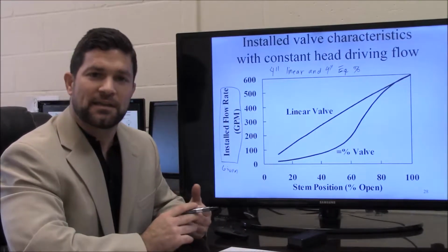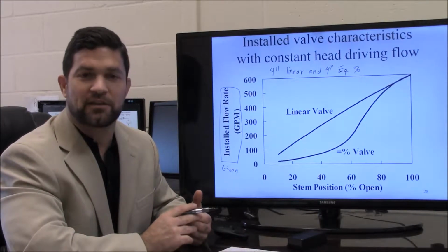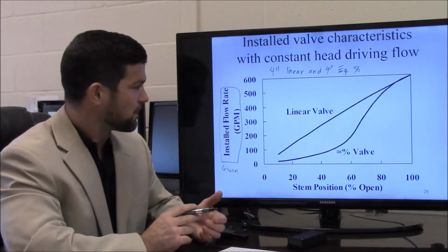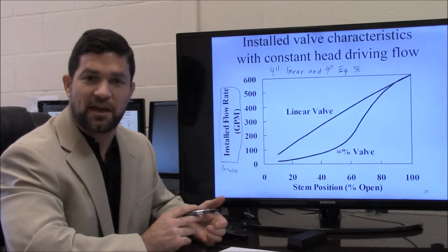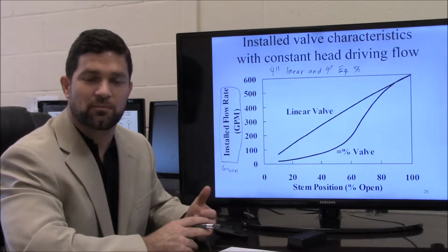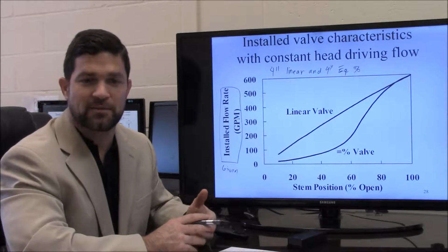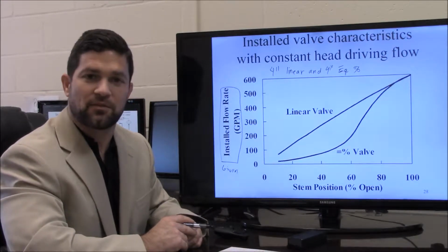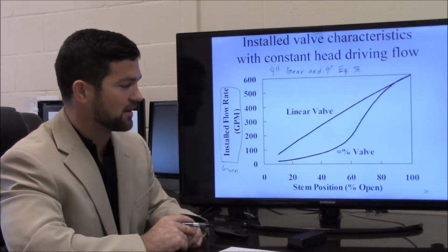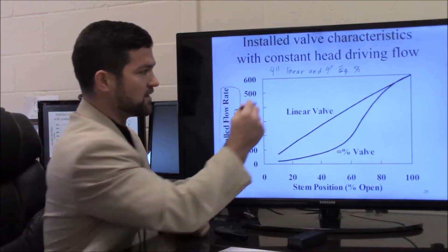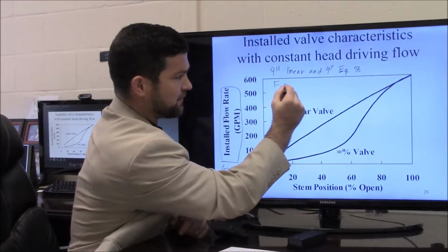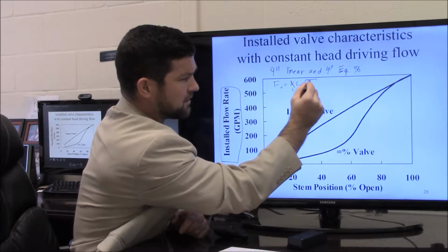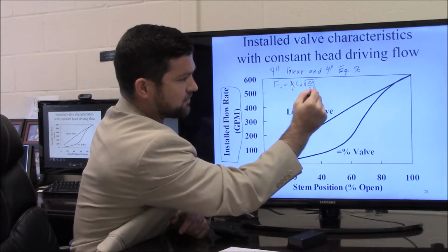Right? So given the flow rates, we calculated the pressure generated based on the hydrostatic head. We calculated the pressure losses associated with the lines, and we got the delta P through the valve. Based on the delta P through the valve, we were able to calculate Cv using Q equals K, actually K equals 1, times Cv square root of delta P over SG.